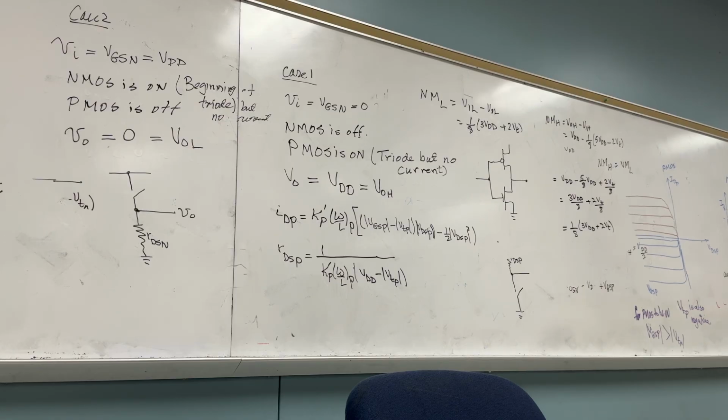In addition, this inverter is going to drive other logic gates. Every logic gate also has a what? An input capacitor. Did you follow me or not? The input capacitor of those gates will be regarded as the load of the driver. Did you get it or not? Yes or no? Yes.